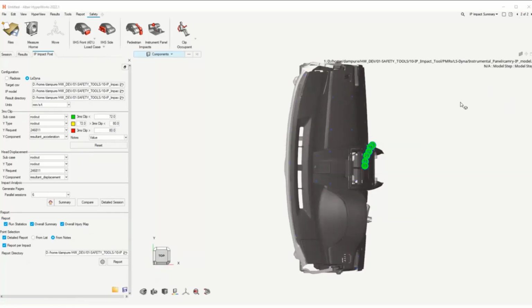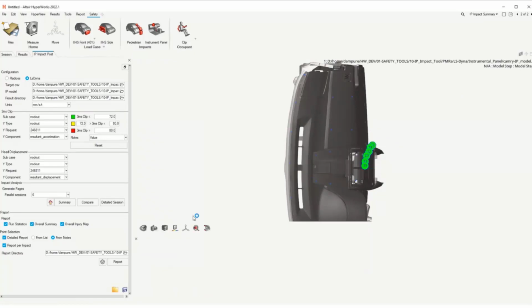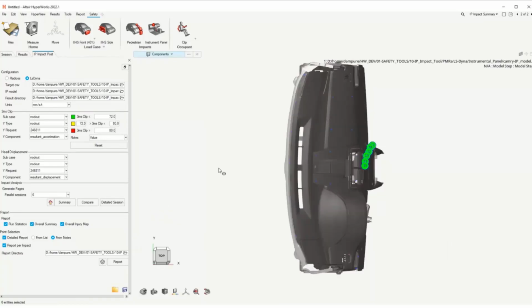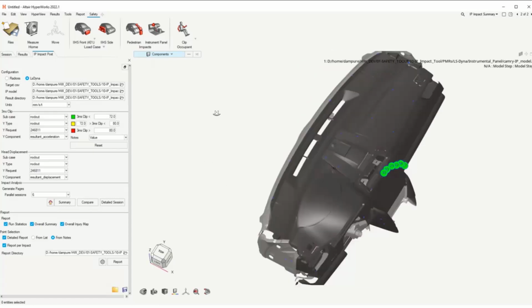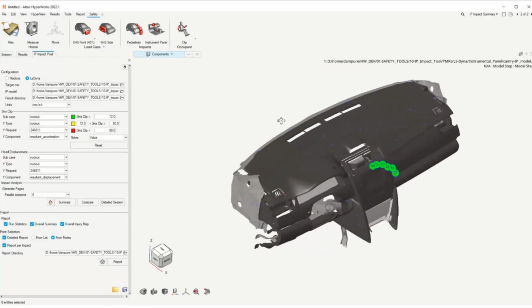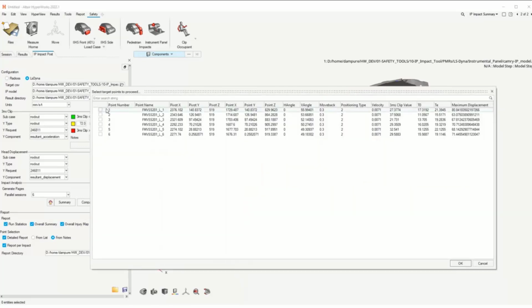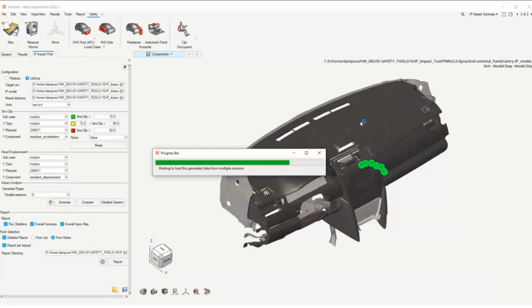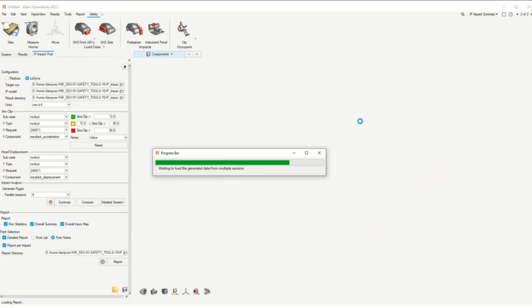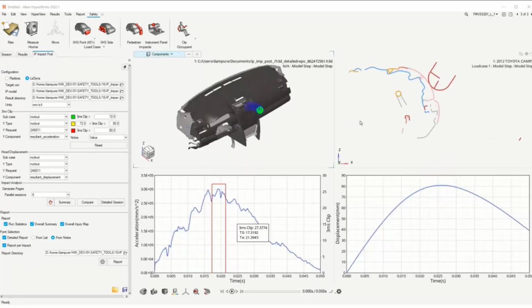and get this summary plot on which you have the 3 millisecond clip value on the node on the IP at the impact location. And if you wish, you can also have more detailed post-processing for given points or a selection of impact locations. Here, just selecting one to show you the detailed report, or the detailed page, for one point.